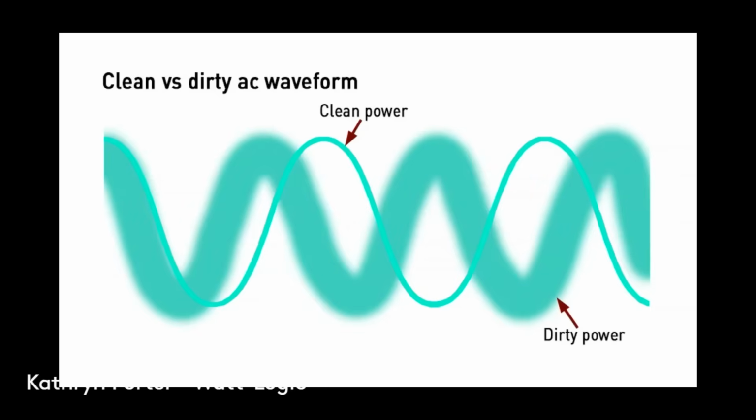Batteries can produce synthetic inertia because they can inject current very quickly, which is useful when frequency is falling, but wind and solar can't do that. Now, in theory, they could using something called grid-forming power electronics, but there are very few of those actually in use, partly because of technical difficulties and partly because the wind and solar generators would have to keep some of their capacity in reserve to use for inertia support, and if you're not using your whole capacity, that has an economic impact, and the frameworks to compensate for that haven't really been created yet.